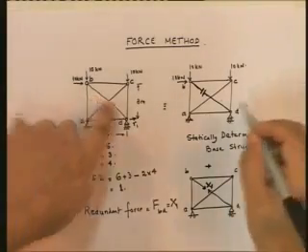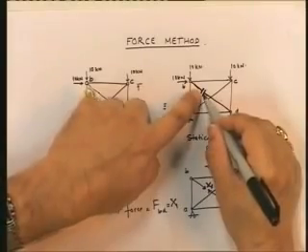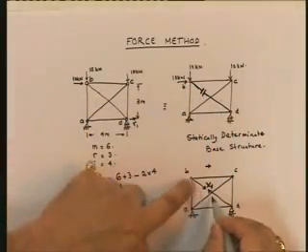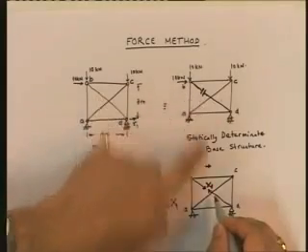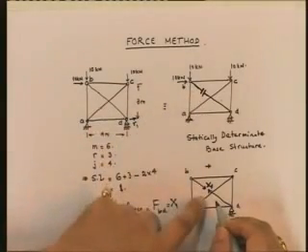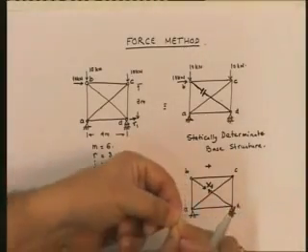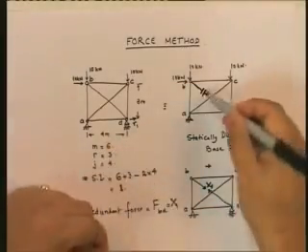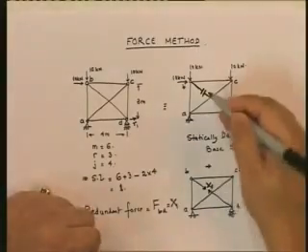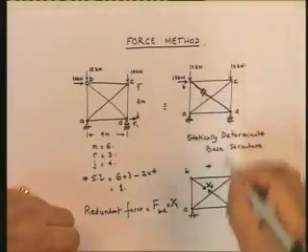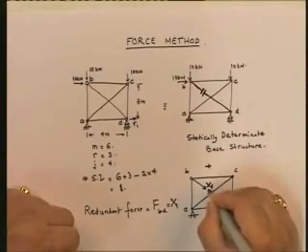What we do is, we find out how much this has opened by, and then add the two, and the two together have to add up to 0, because the point cannot go anywhere. The point is stuck to each other. So that is the independent equation. We need to find out how much displacement I get at this point, and how much displacement I get at this point.